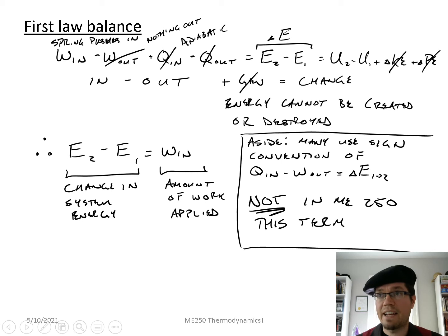If you know that you're adding energy to something, that you're heating it up or cooling it down, you know that that is a Q in or a Q out. If you're compressing it, you're probably bringing work into it. If you're expanding it, work out. Use your intuition. And once you're done the question, if you've discovered that a value you were solving for comes out as a negative value, that just means your intuition was incorrect, so switch it. If it was an in, switch it for an out. If it was an out, switch it for an in.